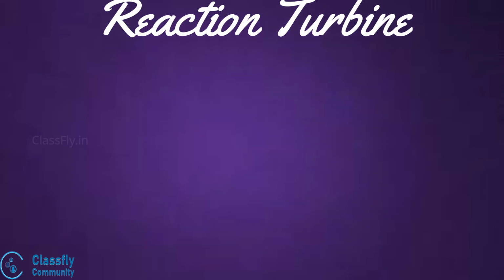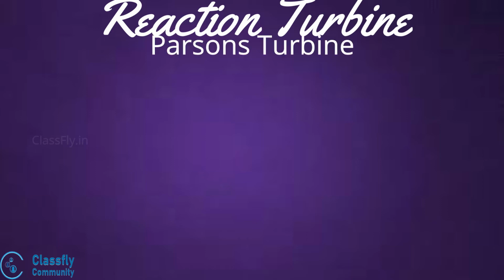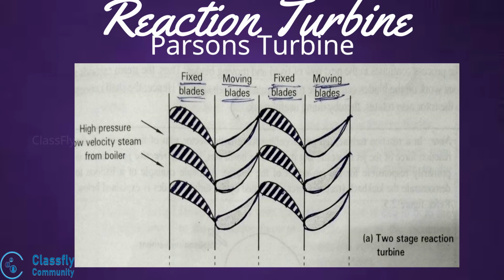Next, let us study the working of a reaction turbine with the example of the Parsons turbine. Well, this turbine was invented by Sir Charles Parsons. This turbine runs by the reactive forces set up by the steam rather than the impulsive forces. This turbine consists of alternate rows of fixed and moving blades. The fixed blades are fixed to a stationary casing, while the moving blades are mounted to the periphery of a rotating wheel called a rotor. This rotor is connected to a shaft.